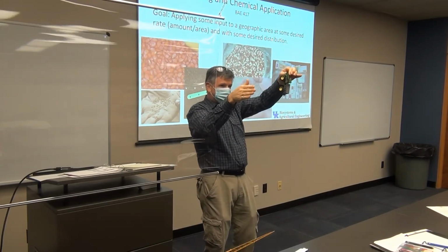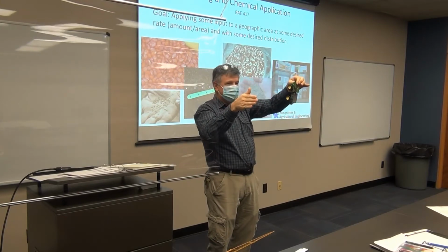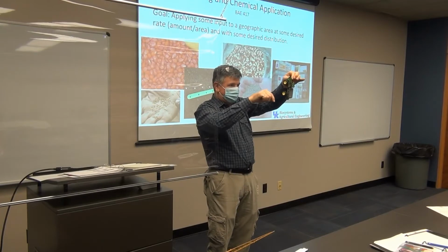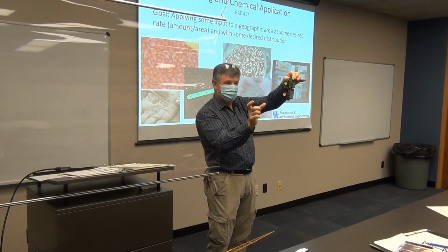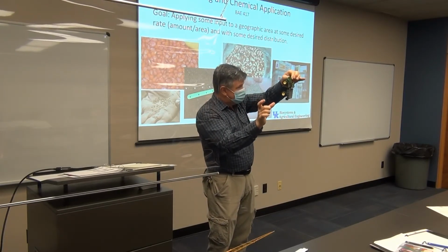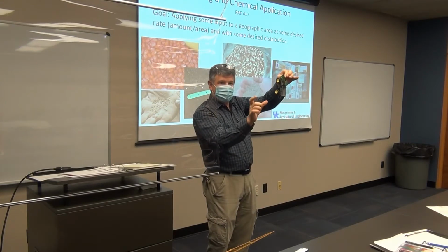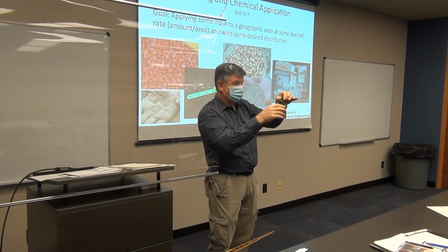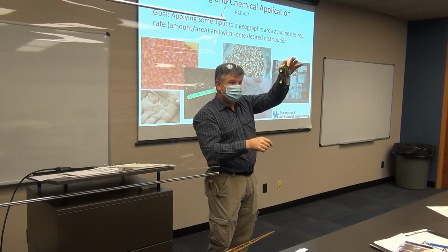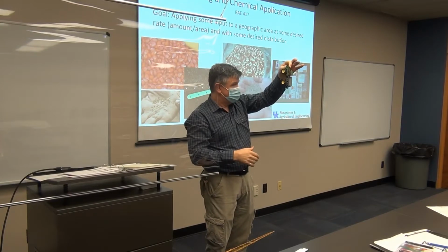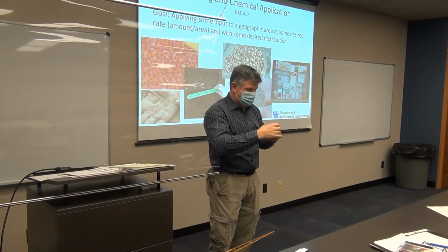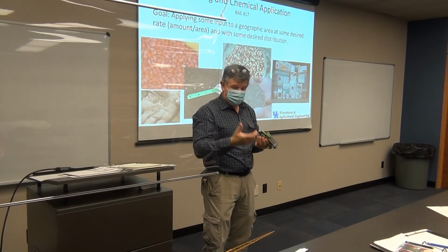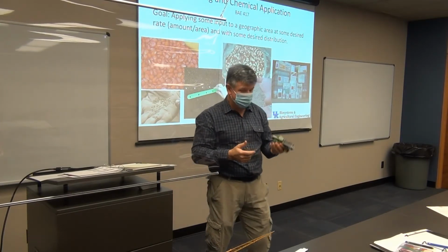But now what about out to the side of the machine? What's going to happen? Now I'm going to have some issues, because some particles will fly further out the side than some other particles. And so out here, I can get some stratification in that pattern. So I'm going to get some particles of a certain kind, and I could get streaking, and we actually do see that sometimes in this type of application. So that's one of the things that people work hard on in terms of engineering. How do I keep that from happening, keep weird things from going on?